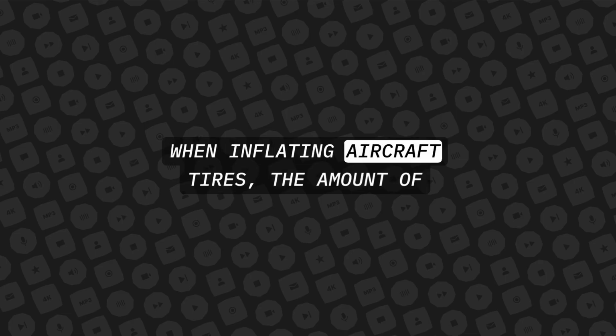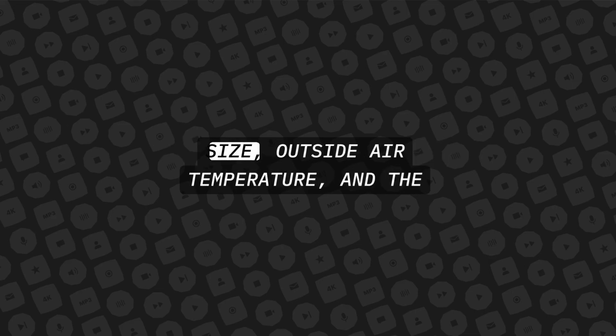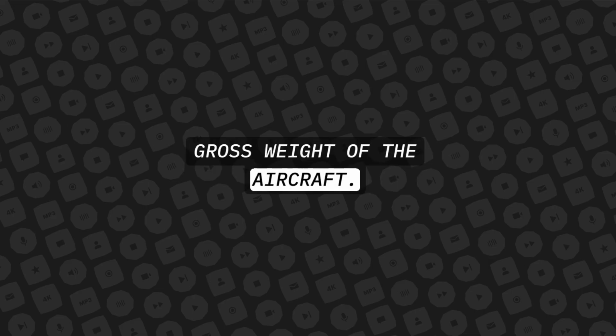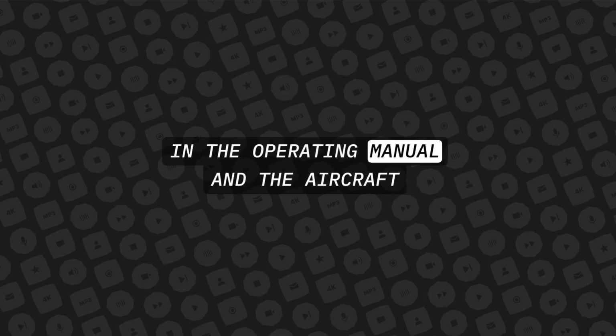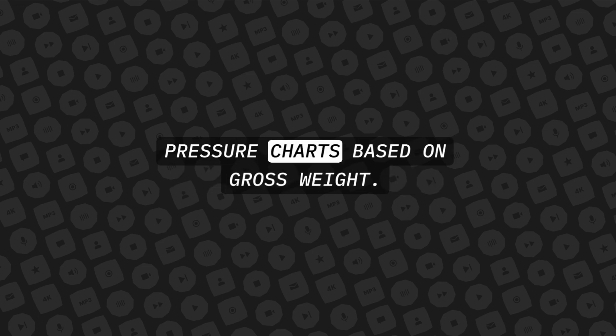When inflating aircraft tires, the amount of pressure is determined by such factors as tire size, outside air temperature, and the gross weight of the aircraft. Specific tire inflation information may be found in the operating manual and the aircraft maintenance manual in special tire inflation pressure charts based on gross weight.